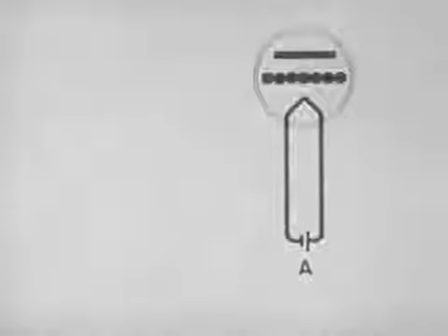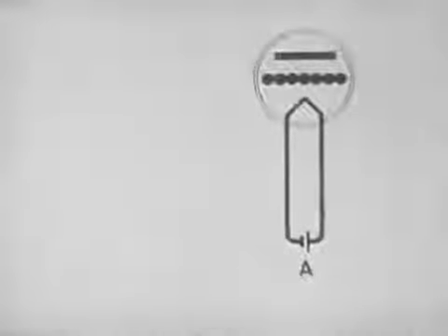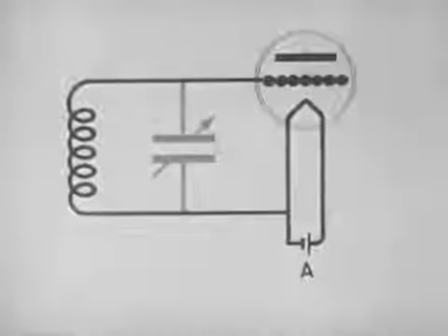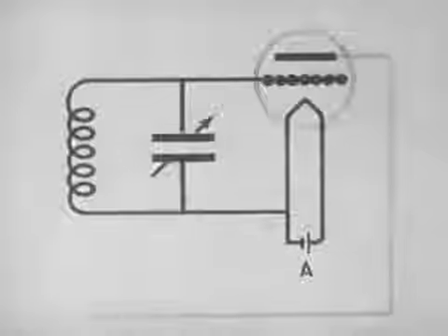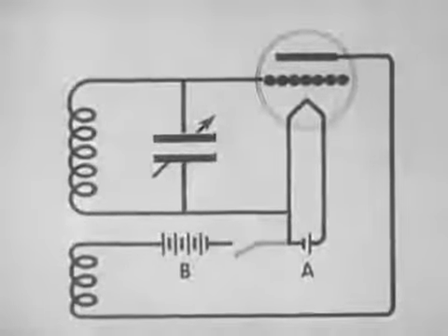The vacuum tube is also used in the transmission or sending station to generate radio frequency currents. In a Tickler-type oscillator, the grid circuit contains a coil and a variable condenser. The plate is connected through a coil, B battery, and a key to the filament circuit.